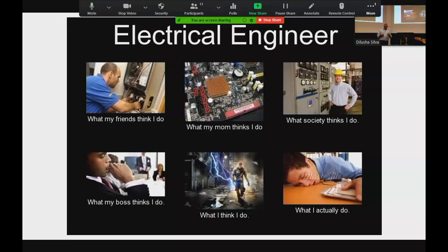I'll give you a hint. It mustn't fail closed. It needs to fail open. Yeah. So a lot of people, especially with control systems. So what you want to do with a coil that's driving a contactor is, when you want to use the machine, have it powered on. That way, if you have any form of loss of power, it de-energizes the coil, opens the contact.